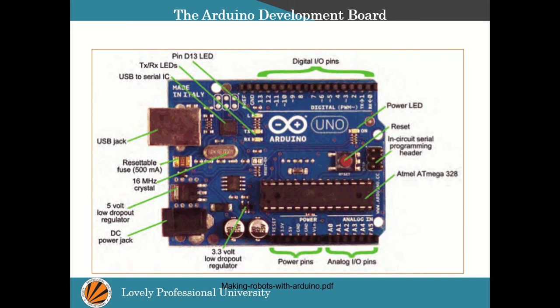So pin number 13 is by default connected with this LED. In case you want to use an onboard LED, you can always use digital pin number 13, so that you need not connect any external hardware just for testing purposes. Otherwise, we can always connect the hardware via these external input output pins.